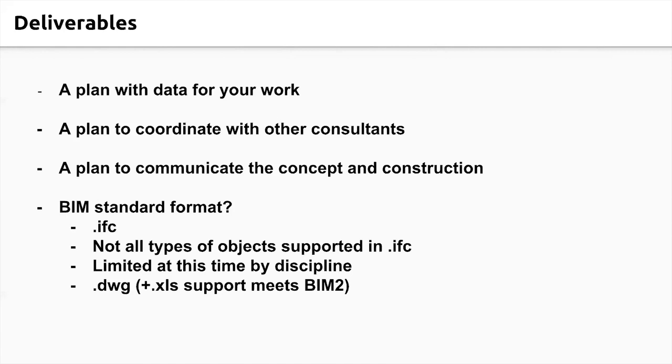But there are some major flaws with it in that not all types of objects are actually supported in IFC. If you had a chance to look into it, it basically takes every object in the drawing and combines it with data, but not all of them. It doesn't have definitions for every type of object in there. So one important thing is, there's no actual definition for a tree to be able to export into any other program that might use IFC and then import that IFC. So you lose a lot in there, and there isn't anything perfect that way. So it's limited at this time mostly by discipline.